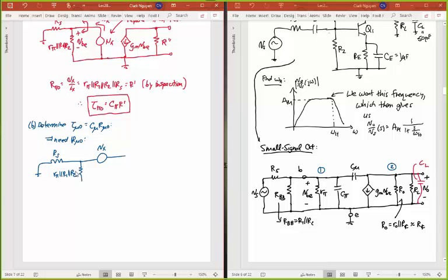Okay, so I have my test voltage source. This is going to ground, and across this I have voltage VBE. And so on this side, I've got IX heading in that direction, which means my plus and minus terminals for my test voltage source are going that way. From here, I have that current source, the voltage controlled current source, that's equal to the GM of my device, a small signal parameter, times VBE. And then finally out here I have my output resistance in parallel with all those other resistances, which remember I called R double prime last time. So I'll just use that shorthand and call that R double prime there.